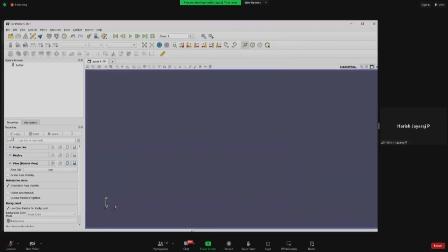After you open ParaView, this apply button here will be highlighted with green color. You have to press this. Then you will see something like a line sort of thing on the window. After you see that, you have to press this button on the top. So the plus Y.